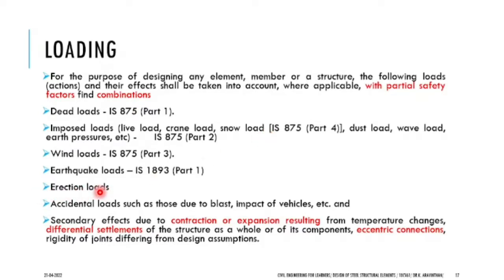Erection load in the sense, see, steel members have to be erected. If you are making any workshop or constructing any steel structure, there will be a crane. The crane will be erecting all the members. The steel members cannot be erected by humans, so you need equipment. Whenever you have equipment, even that equipment has some load. Yes or no? If you are constructing a workshop with 2 floors and erecting the second floor members, you will be having the cranes. The crane in some cases has to be there on your structure. So this is what they are saying in erection load.